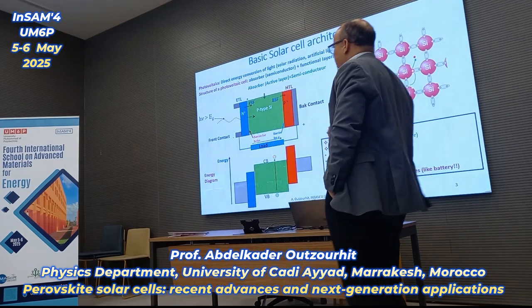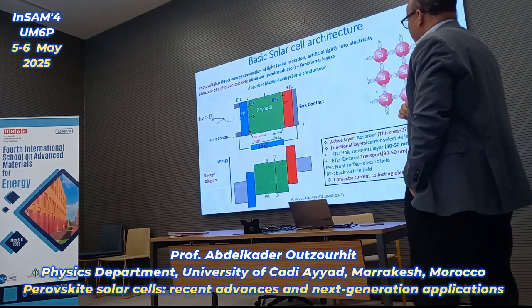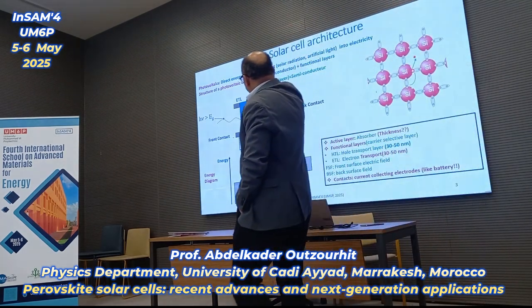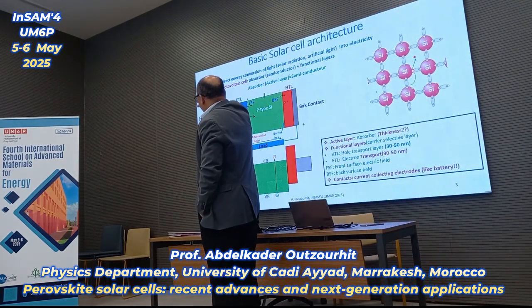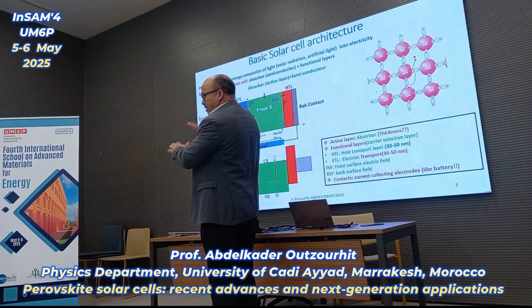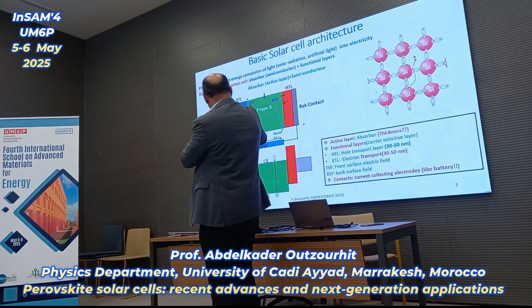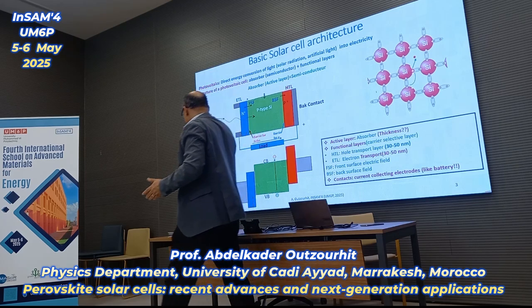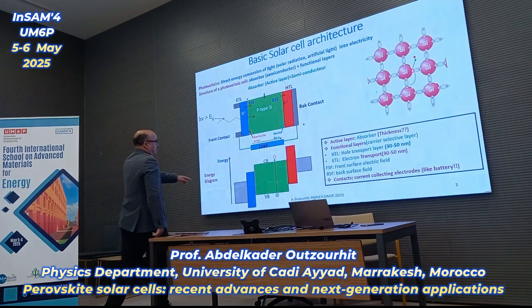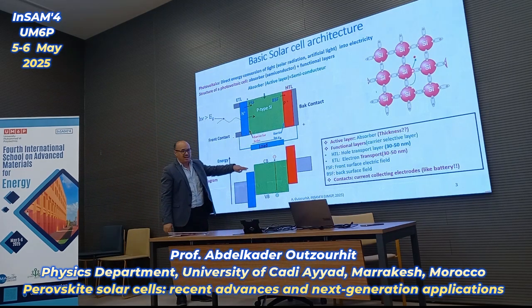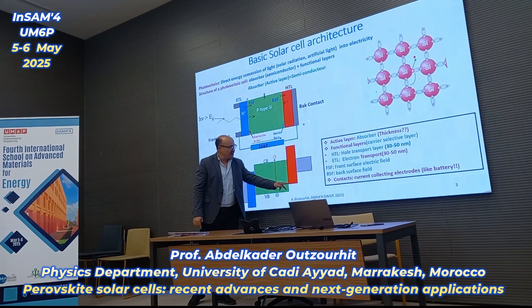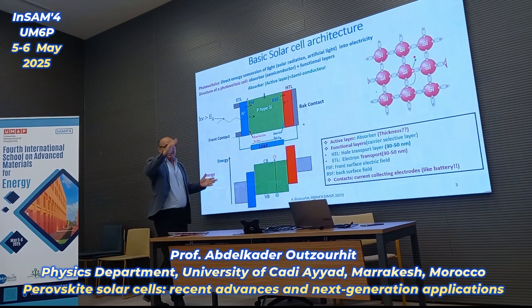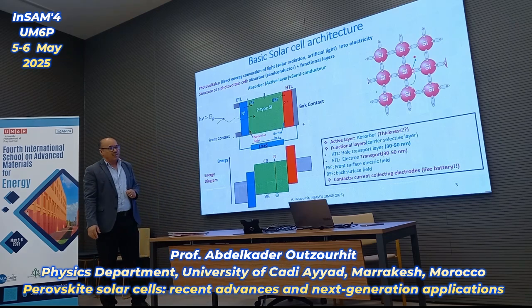Those are just some notations for the doping level. So from the energetic point of view, the energy levels in this structure are designed so that electrons can go down the steps like this. Because electrons like to lower their energy, they can come this way along these steps, and the holes can go up the stairs like that. That's how they also lower their energy.